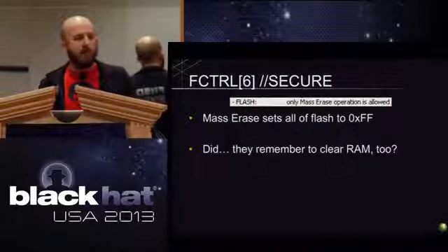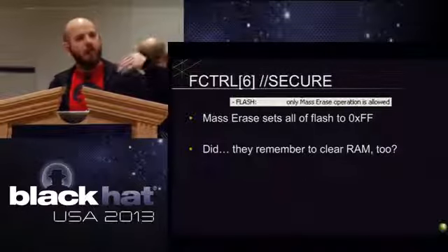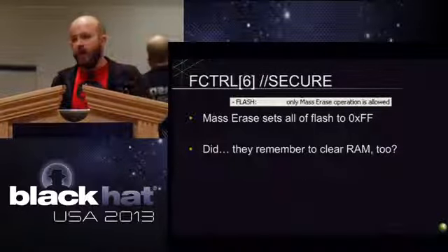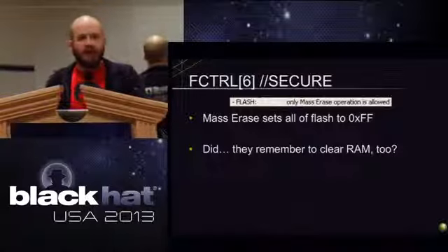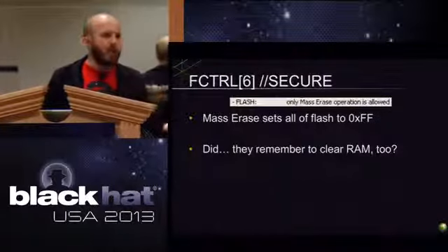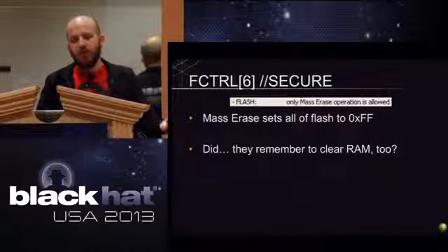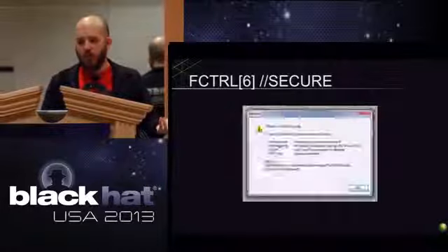So the common way these guys will do it, and the MSP430 does it the same way, and others, is that without being able to light up the full debugging interface, you can perform a mass erase. So what does that do, right? It resets all the flash to FF, but there's an important consideration here: did they also think to clear all the other locations? Because that's not the only location where something sensitive is stored.